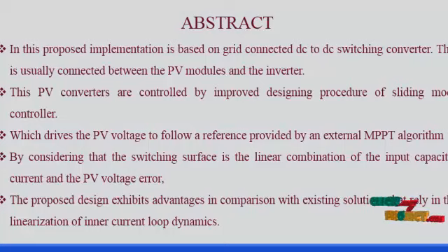The proposed power and frequency characteristics of the hybrid unit and of the microgrid operating conditions are such that the hybrid unit may supply the maximum PV power, match the load and/or charge the battery while maintaining the power balance in the microgrid and respecting the battery state of charge limits. These features are achieved without relying on a central management system or communication, as most of the existing algorithms do. The control strategy is implemented using a multi-loop controller which provides smooth and autonomous transition between the operating scenarios, and this proposed implementation is done in the MATLAB simulating environment.